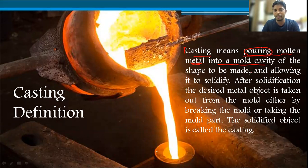We have some hollow cavity in which we are filling this molten material, of the shape to be made. Whatever shape is required, accordingly we make the mold cavity and then fill it. Then we allow it to solidify. After the solidification, the desired metal object is taken out from the mold either by breaking the mold or taking the mold part out. The solidified object is called a casting.